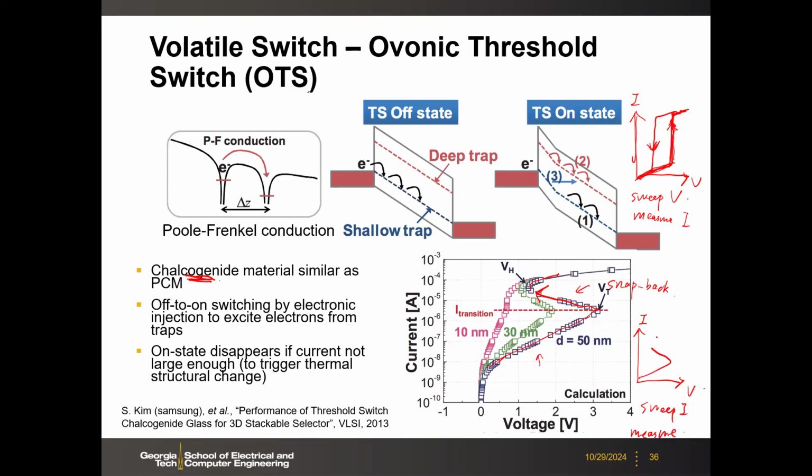Then you will see this S-shape, right? Because current is continuous, you ramp up the current and measure what is the voltage here. Then the voltage will have this snapback. Essentially, that's the same. Actually, if you do that on the same plot, if you measure the current, then basically you collect this point and this point in this S shape versus this N shape. So you got the difference? It's the same thing, just a different measurement scheme.